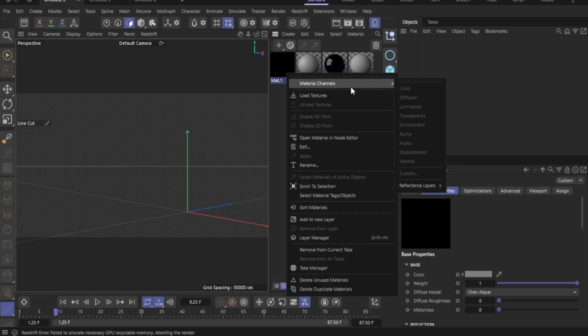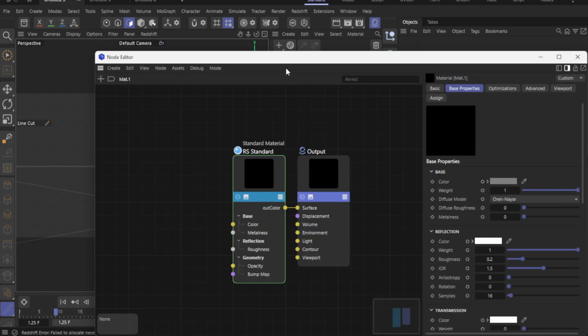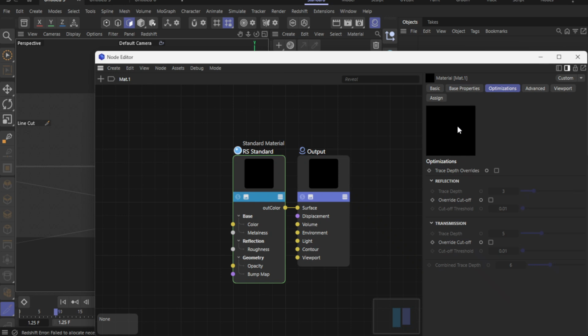To actually see the video play in the viewport, enable the Animated Preview. In the Material Editor, go to the Editor tab and check Animate Preview. With that on, the material's thumbnail and the texture in the viewport will play back in sync with your timeline, making it much easier to line up animation and timing. You'll notice the texture updates as you move through frames so you can quickly judge pacing and placement.